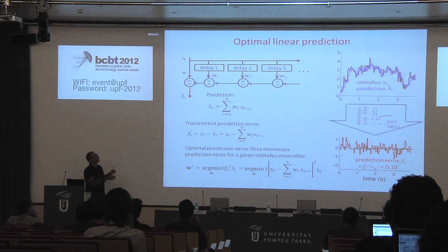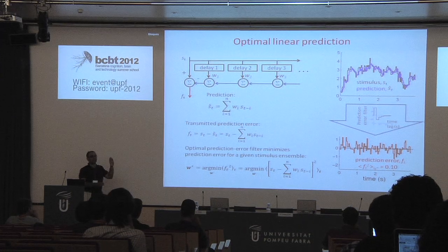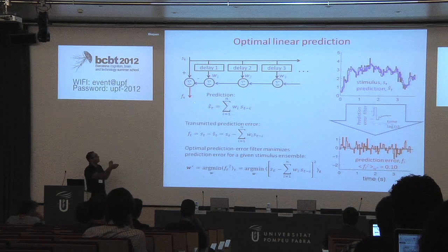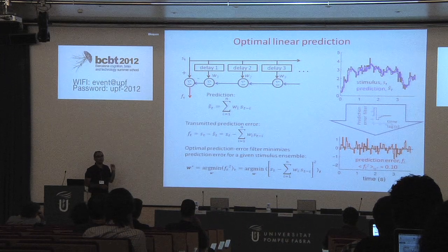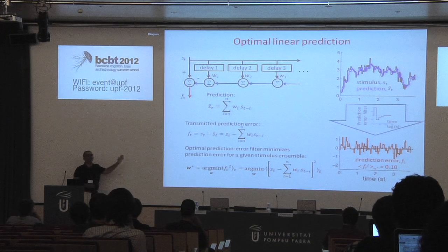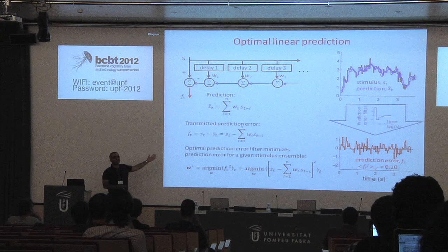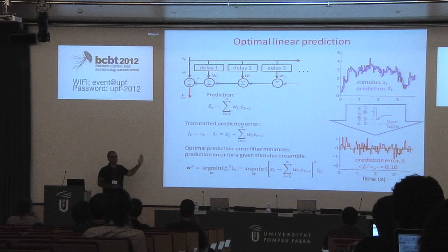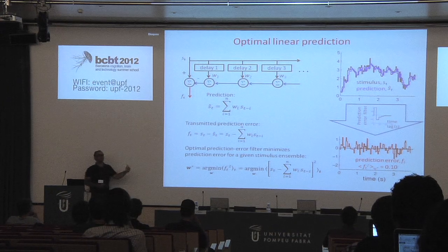And then we would have some sort of a gain that comes before the actual communication channel, which will scale up the signal relative to the noise that will be added. So that's where your small variations will get amplified relative to the contaminated noise and transmission. Okay. Does that answer your question? So I wanted to avoid all those issues in the example that I gave you initially by discretizing the signal at values which exceed the amplitude of noise. So you don't have to worry about it. But in reality, yes, of course, there is transmission noise, and that's what happens.